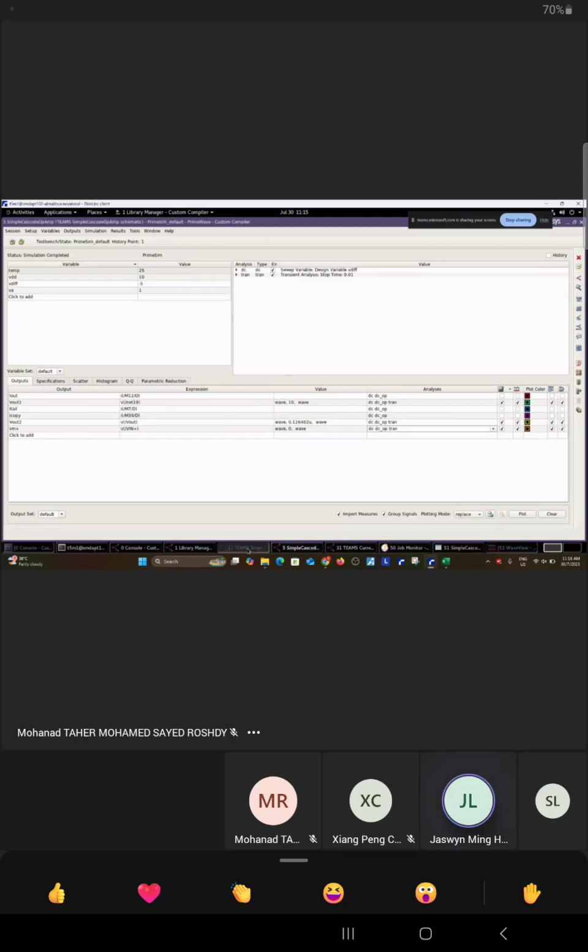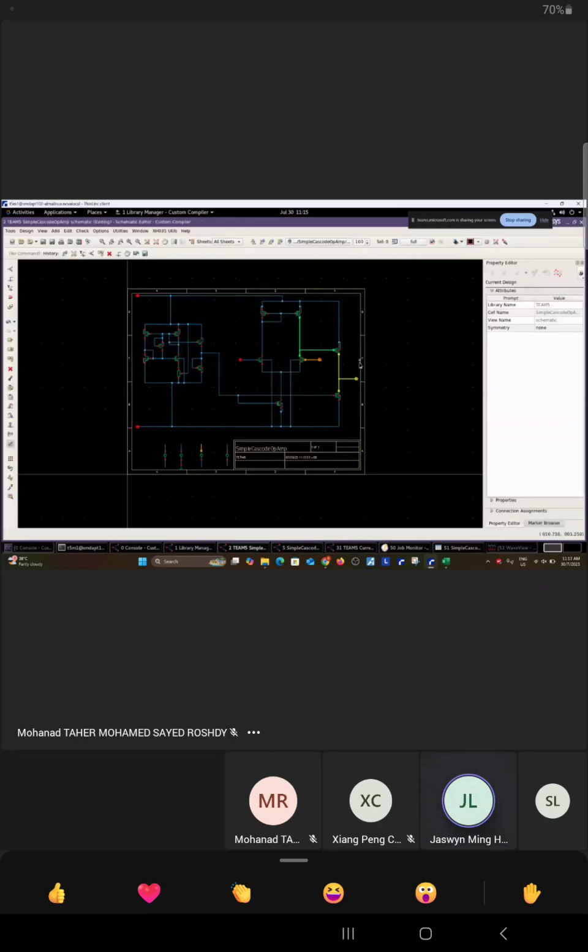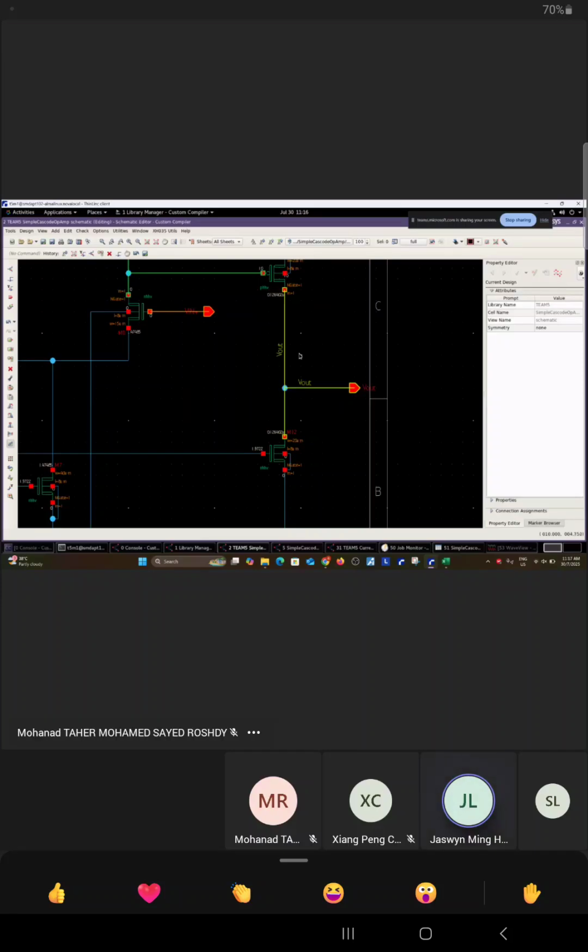I think they have the library for you to take, right? Yeah, you put in the capacitor here. Yeah, mirror, you just put it here. You connect the V out 2 to V out 1. Usually you connect compensation between the input and output. So this is the input, this is the output. You just put it here.